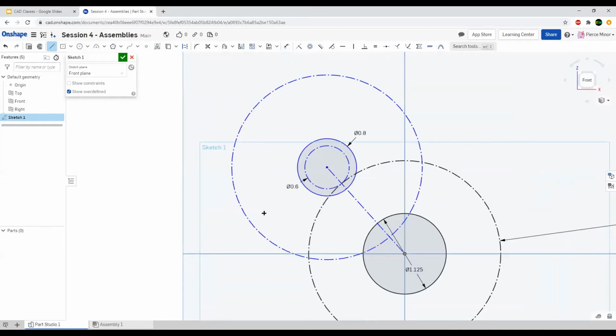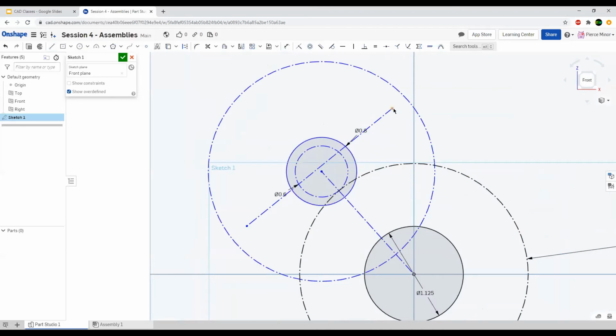I'll just draw a line across here. It sounds good to me. However, the mounting points are not centered on the Neos. They're all an equal distance from the center of the Neo. So if I'm trying to model two opposite points, the best way to do that is take the point at the center of this circle and go to this line and create a midpoint. This ensures that this point and this point are always going to be the same distance from the center, no matter what